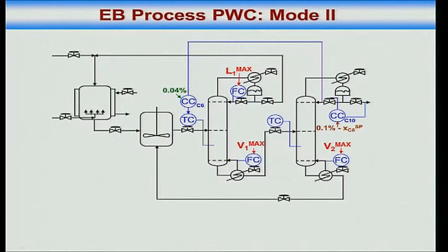And then this temperature set point is adjusted to maintain the benzene impurity in the product at 0.04%, which my optimizer gave me. So why is it linked to reflux? The reflux is the product. Distillate and reflux are the same, right? It's just ease of drawing. That's all. So the product benzene impurity is setting the temperature set point.